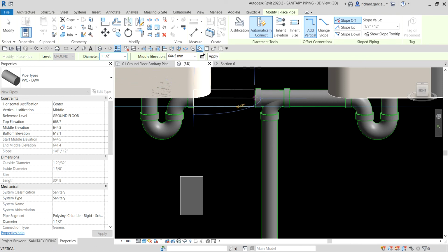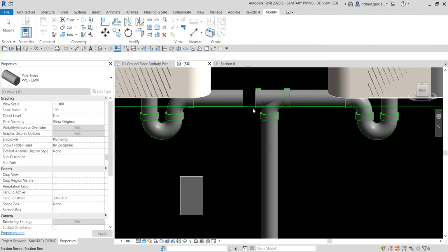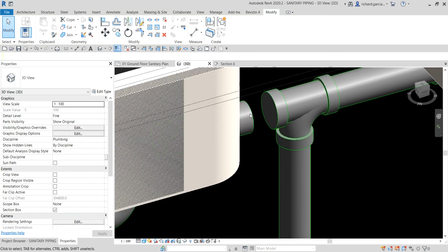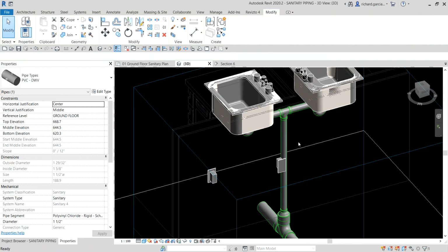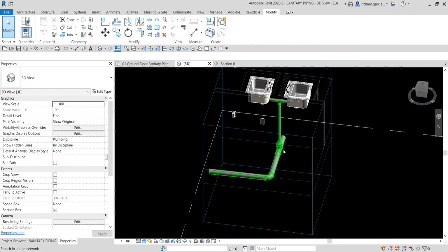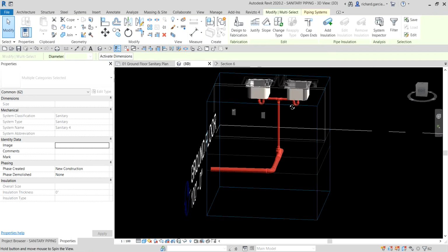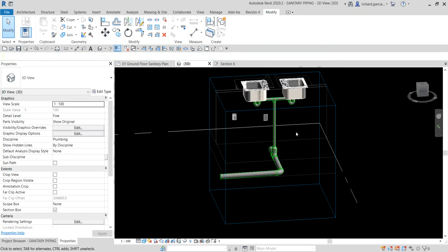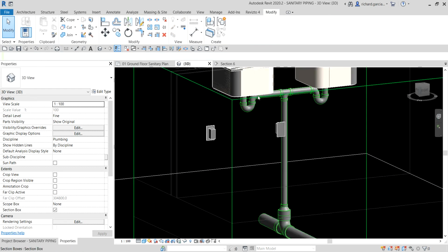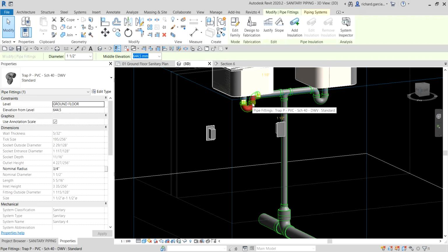And then let's try to connect this here. There you go. Okay, so click that, drag, tab, and then click. There you go. So let's see the connection now. Okay, so the connection is now working properly. As you can see, the piping is really interesting because you'll be able to think a lot of ways to do the piping. You can actually create another pipe here, just a short pipe, and then what you can do is you can turn this, you can rotate this.